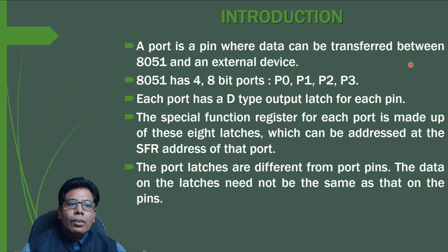The topic for today is 8051 input output ports. Introduction. A port is a pin where data can be transferred between 8051 and external device. 8051 has four 8-bit ports P0, P1, P2 and P3. Each port has a D-type output latch for each pin. The special function register for each port is made up of these 8 latches, which can be addressed at the SFR address of the port.